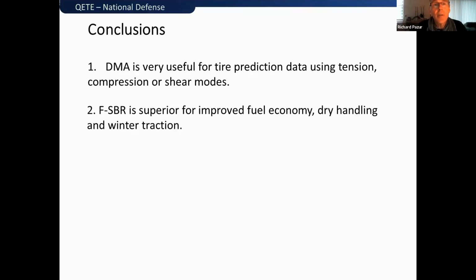What we saw in the results, the functionalized SBR is superior for improved fuel economy, dry handling, and winter traction. But we found that the regular SBR is superior for ice, wet, and dry traction.